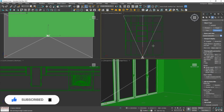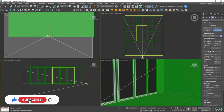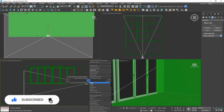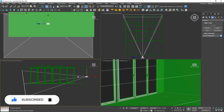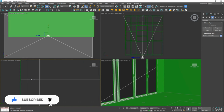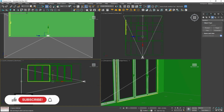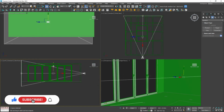like this. Then over in the left view, notice that our camera's on the ground, so I'm just going to right click, move camera, and if we move that up, notice that we actually have a camera target, so we can undo that, and we're going to want to select this camera target as well, so we'll hold Control and select that, and now we can move this up into position.